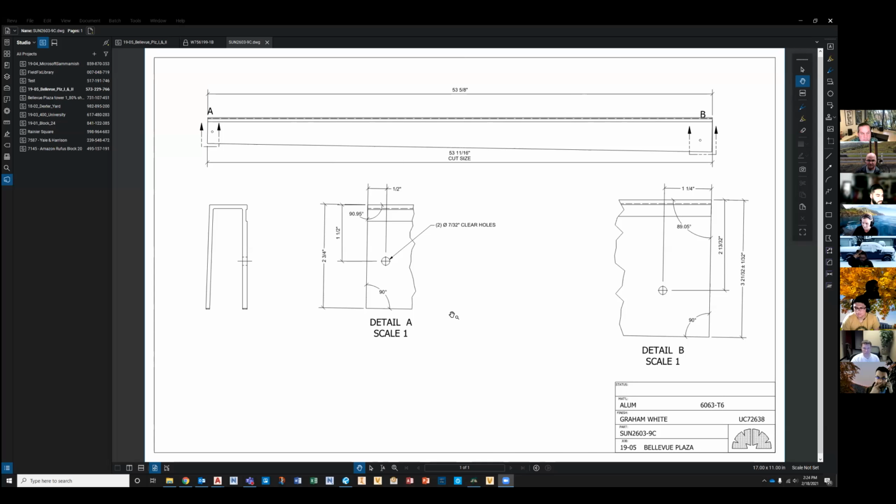Yep. So this is a fab drawing for a fin on a unit, and this is an Inventor part. You place the part in and rotate it to the view you want, and then if you right click and drag, you can place new views off of this view.